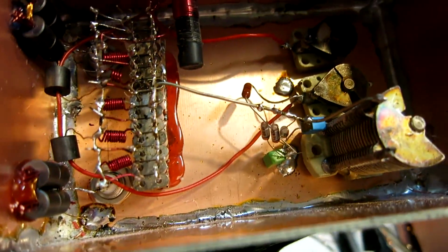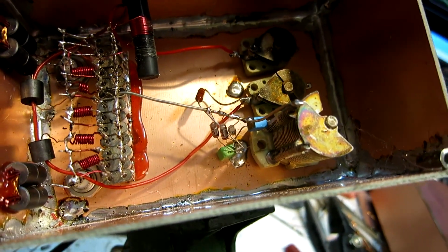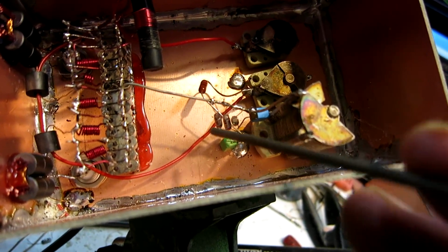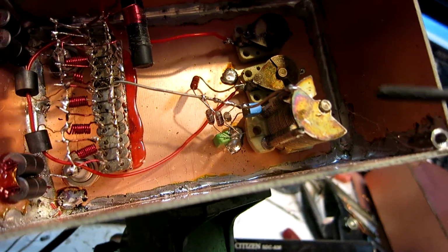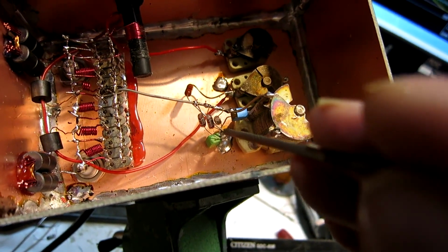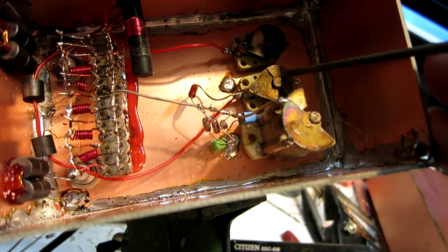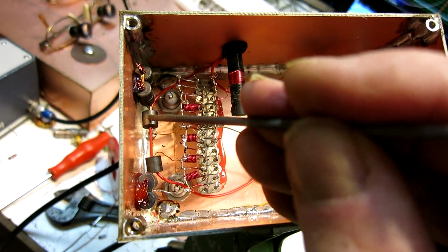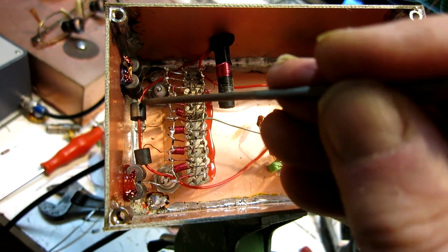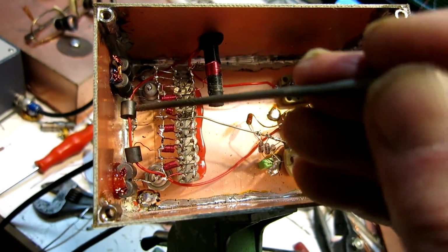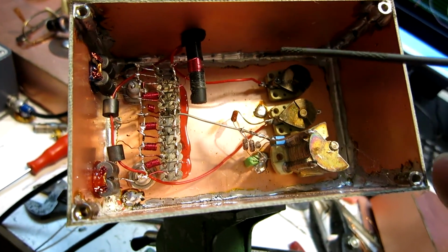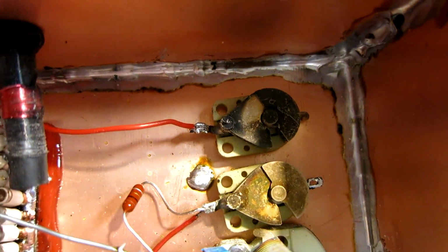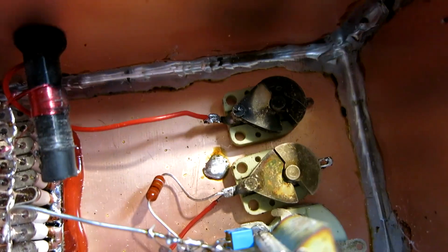I have added a means of cancelling the signal at the bottom of the notch. 1 nanofarad in series with these maybe 400 pF that are in parallel with the tunable capacitor. And from that an inductor and then a capacitor to ground. That is to introduce a variable phase shift. And then the wire goes through 2 ferrite cores that couple to the current. The inductance of these cores is small compared to the impedance we have at this point, which is 450 ohms. And then at the end of the wire, a capacitor to ground. And you can see the capacitor values are small. This way I can get the notch very deep.